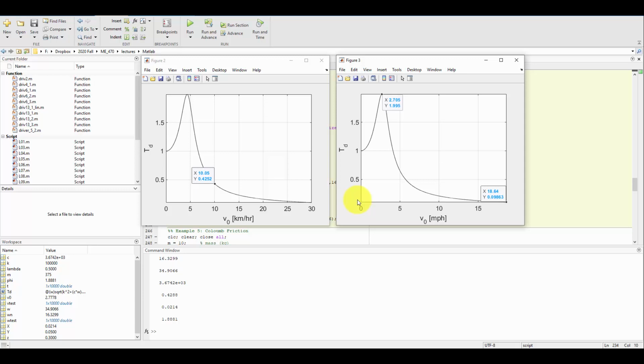So this does not apply to going over something like a speed bump, where that would be kind of a half sine wave where it's going to go up and then be flat at 0. So we don't want to assume that we should go fast over speed bumps for a smoother ride, because that is a different input than we have here. That is not simple harmonic displacement. A half sine wave we'll get into in the next section talking about general forcing.